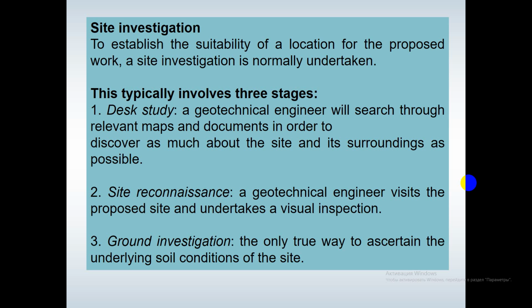For example, the following information will be studied: geological solid and drift maps, hydrogeological maps, ordnance survey maps, including historical versions, aerial photographs, past activities within the area such as mining and waste tips, public utilities, etc.